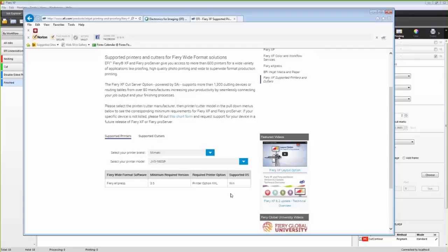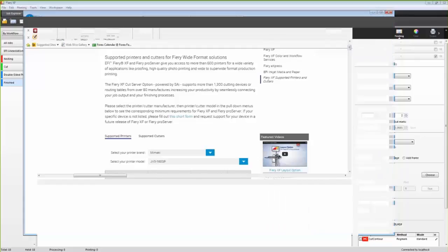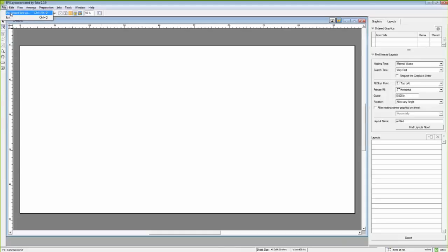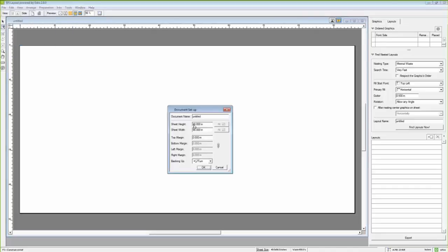Carrie, do we want to take one more before we wrap up? Certainly. Okay, so John, is it possible in the layout tool to export the final layout in the same sheet format as the layout setup? So for example, A4 in and A4 out. Yes, again, with the document setup, go into File, Document Setup, and set exactly the size of sheet that you want. And again, you can go into the preferences and set this for inches or millimeters, centimeters, etc. Set exactly the size you want, and then the layout option will work within those parameters for you.